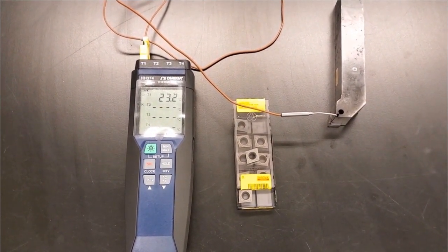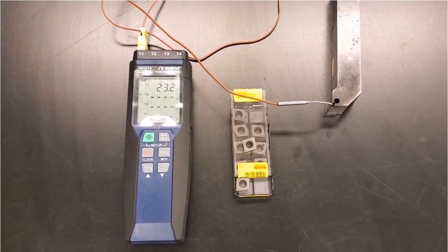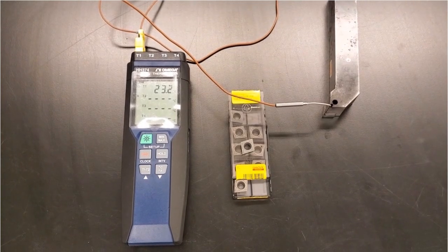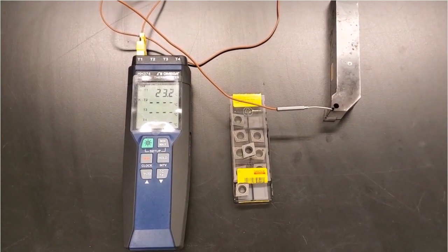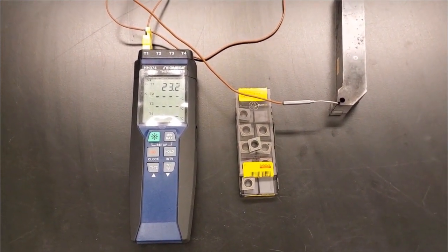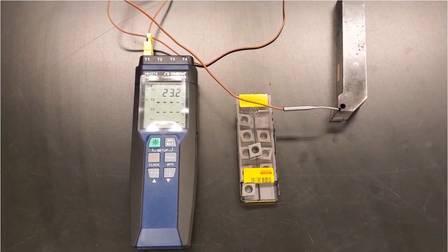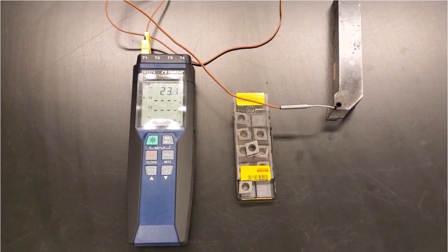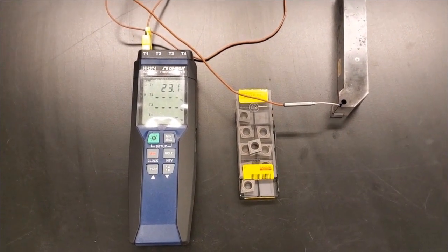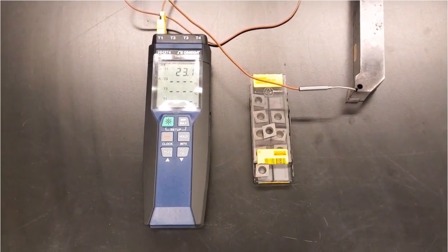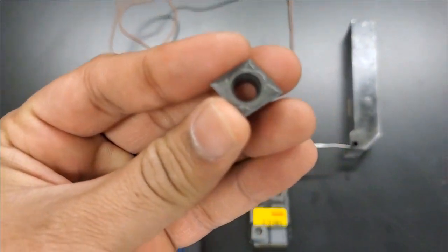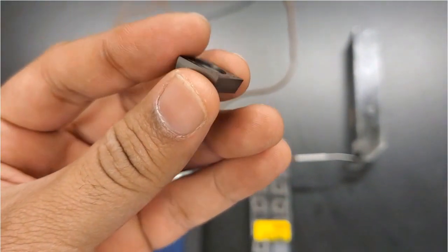Now, the next and very important question is, what temperature are we measuring? And generally, the most significant or generally investigated temperature is that of the tool. Okay, so in machining materials like titanium, the temperature goes up to values sometimes close to 1000 degrees Celsius. And temperature is one of the main reasons for tool wear, and so that's why we want to know what temperatures the tool is exposed to.